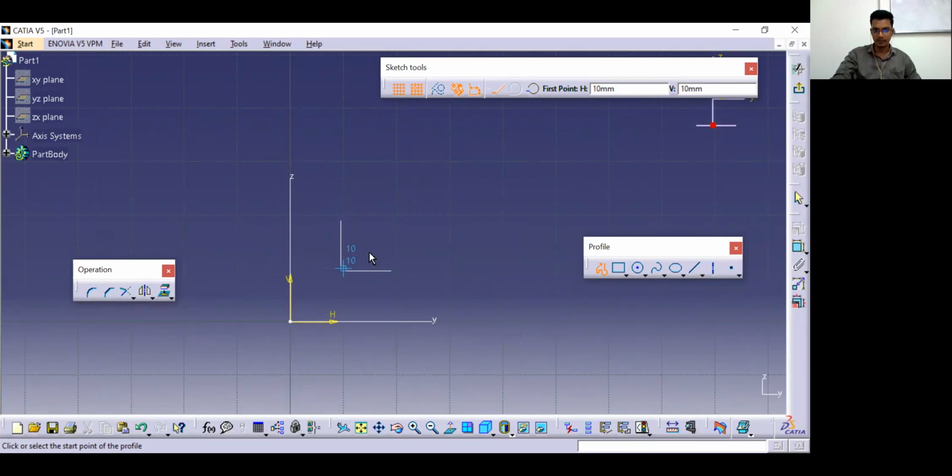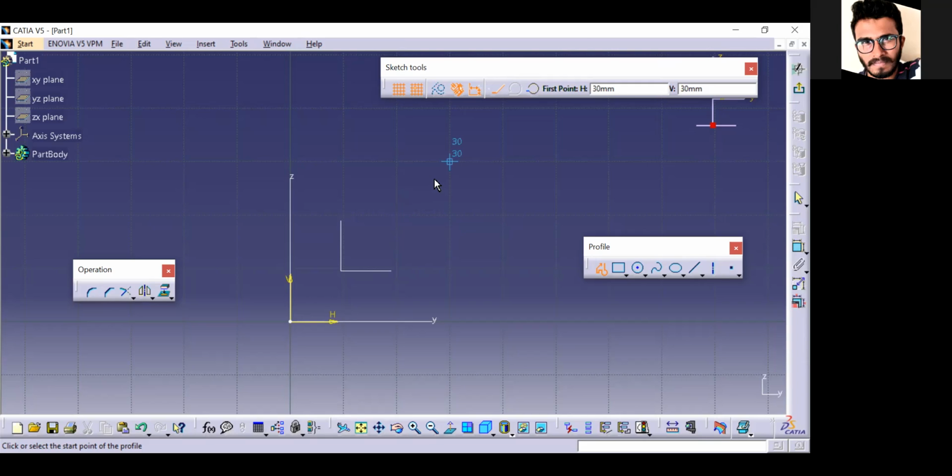See, now it is 10 comma 10. If I move it upwards, it is 20 comma 20. If I move here, 30 comma 20. It is only moving on these grid points, the coordinate points. Very good. Are these the dimensions we give every time in our mechanical drawings? Are we fixed to whole numbers? No, sir. We have to give dimensions in decimals also, but now it is not taking decimals. If you switch this off, you can notice it is moving in decimal points also. Exactly. That's why this should always be off, so that you can draw freely with your desired dimensions.